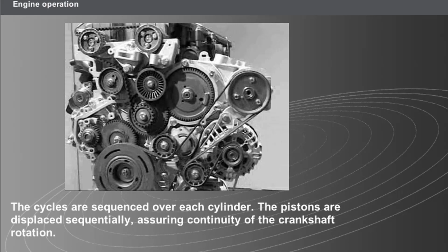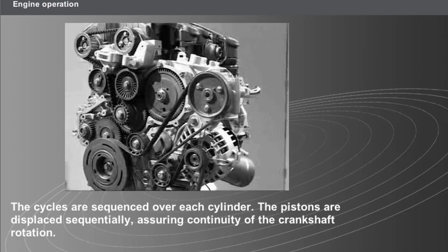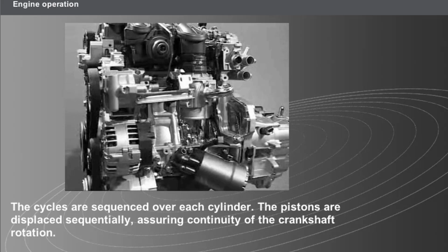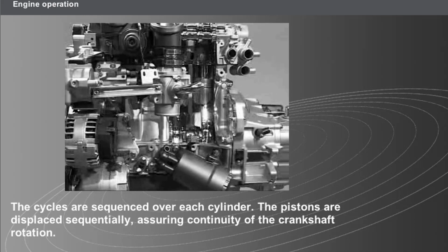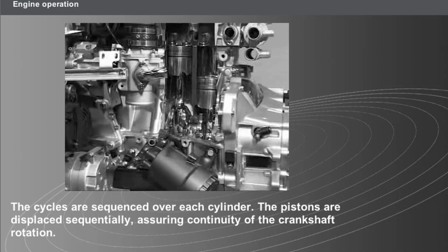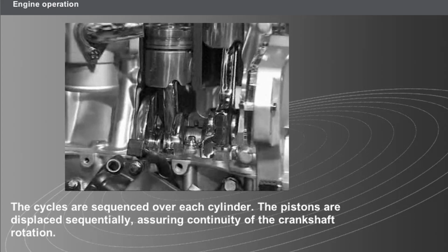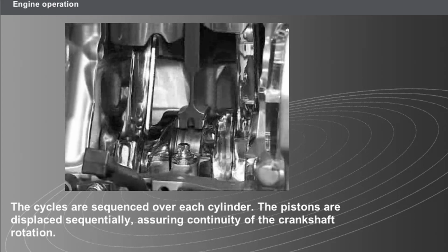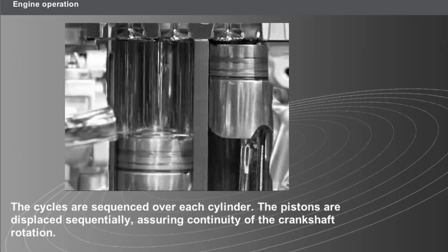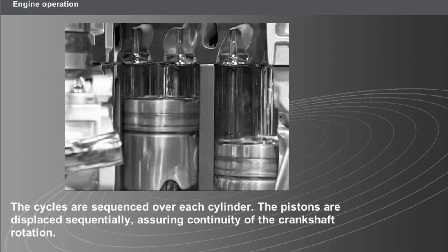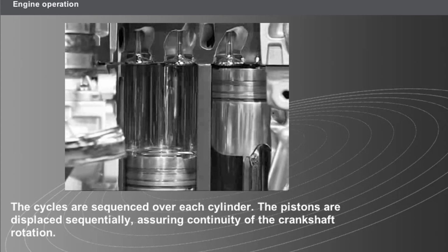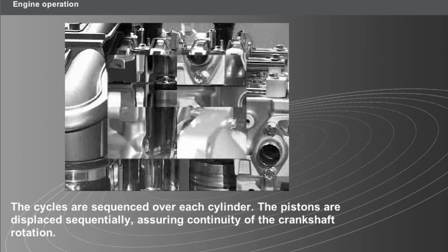In a 4-cylinder engine, the cycles of intake, induction, compression, combustion power stroke and exhaust are sequenced over each cylinder. The timing synchronizes the movement of the camshafts and the crankshaft. The pistons are displaced sequentially, assuring continuity of the crankshaft rotation. The opening and closing of the valves is synchronized in relation to the movement of the pistons.